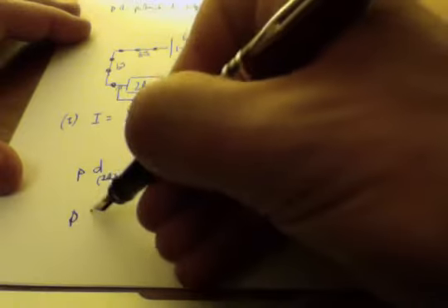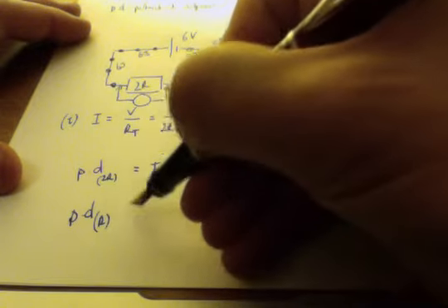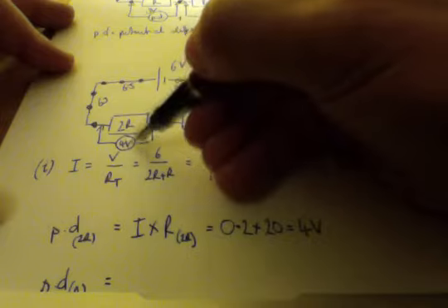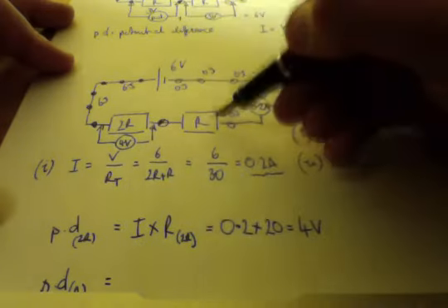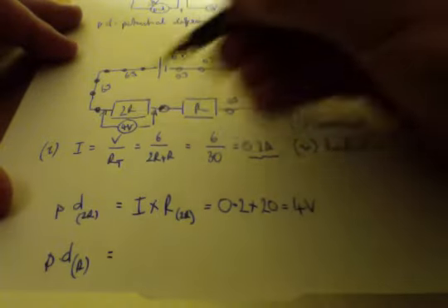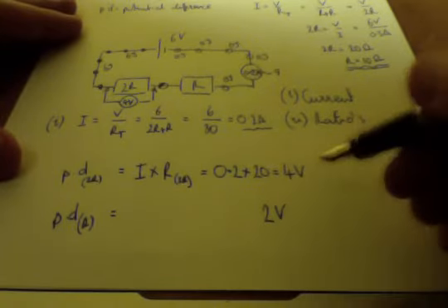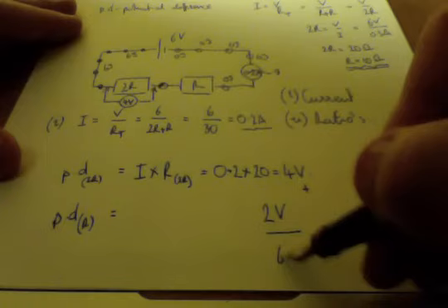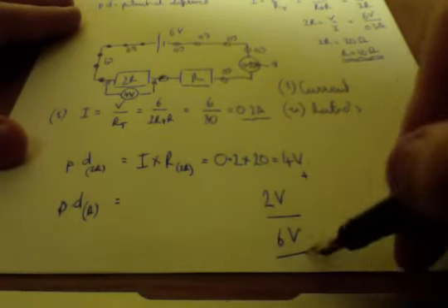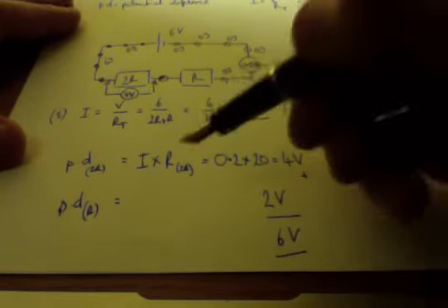Okay, what's the potential difference across the 1R resistor? Well, the very easy way of saying that is we know that 6 volts need to be used over the two, so simply it's 6 minus 4, which gives us 2 volts, because those two must add together to be 6 volts. However, longhand, let's just make sure that works.